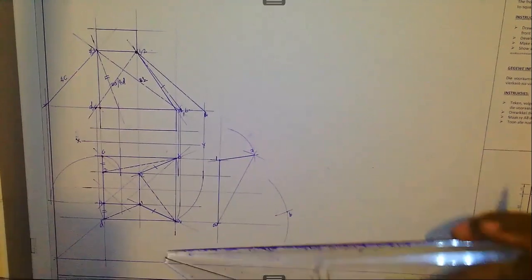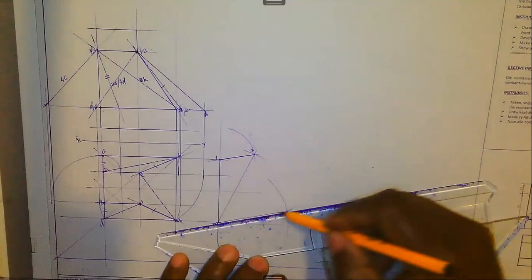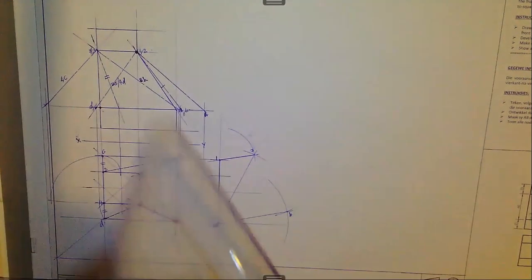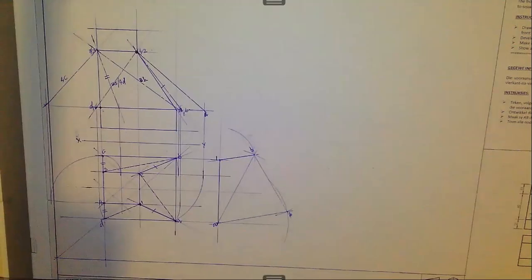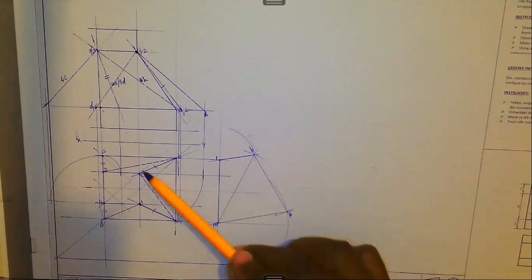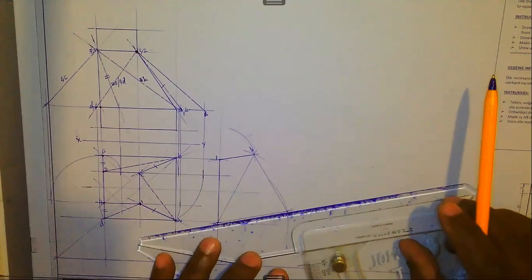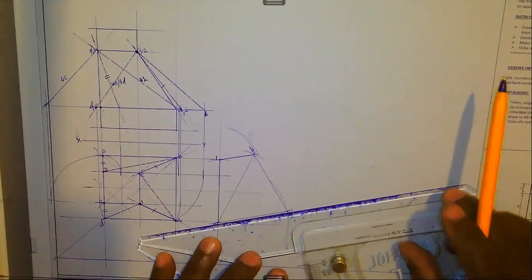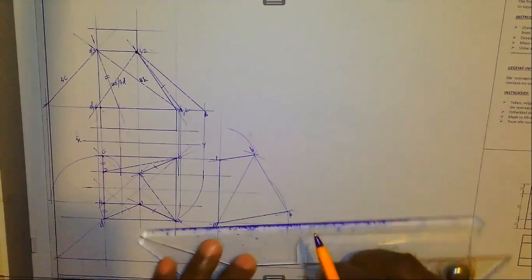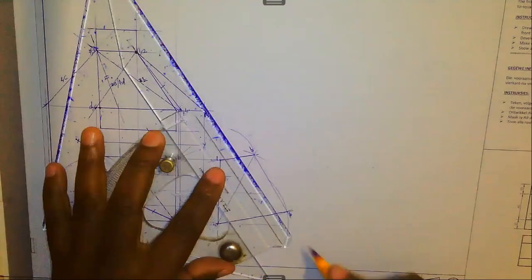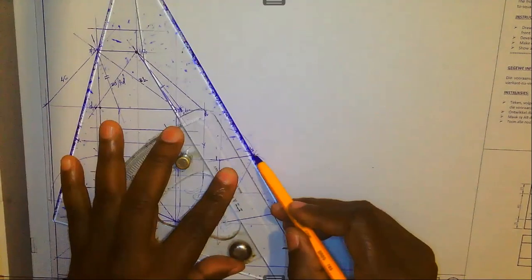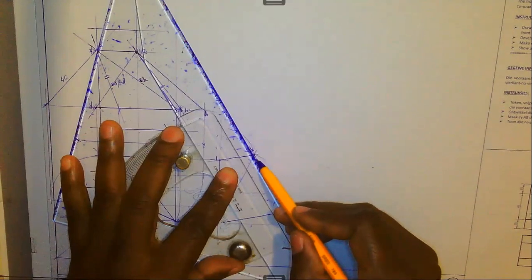Then you connect point A to B and 2 to B like that. That is your first panel. So the true size of this panel is now defined like this. You can outline this from here to there, and show this line from here to there as a fold line because it's going to be folded. Like that. There you go.